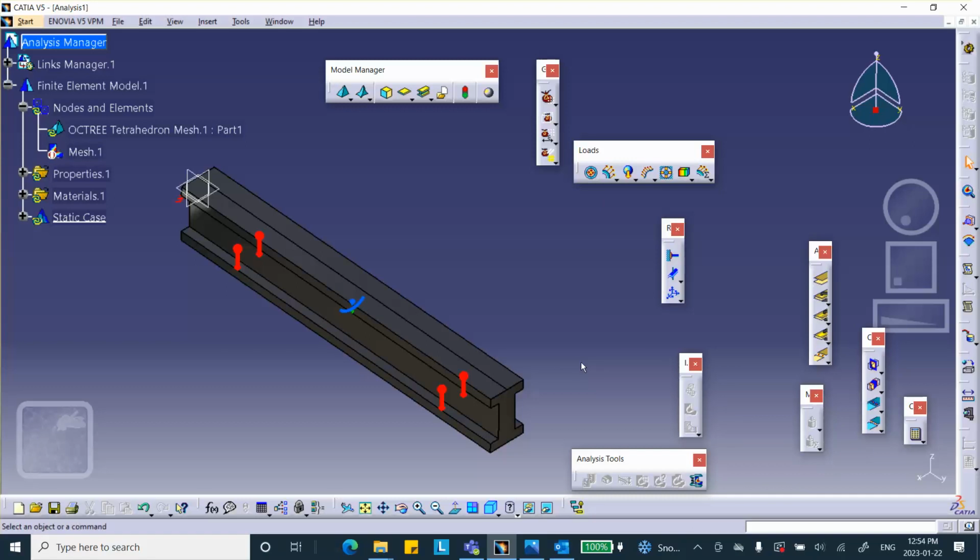And for example, if this was the antenna on your car, mounted vertically, and the car would accelerate along a highway, whatever the acceleration is, this will bend because of the car acceleration. You would apply acceleration in the proper direction, maybe X or Y, depending on the direction of travel of the car, and that'll give you the deflection and stress distribution. So let me save this thing.